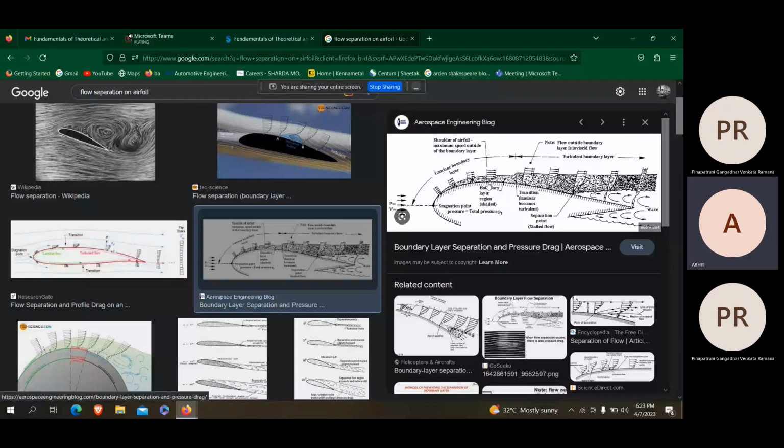And what does that pitot probe measure? Stagnation pressure will be measured at the mouth of the pitot tube, at the entry point, and static pressure will be on the surface of the tube. So it measures both pressures, I think, like a pitot static tube.